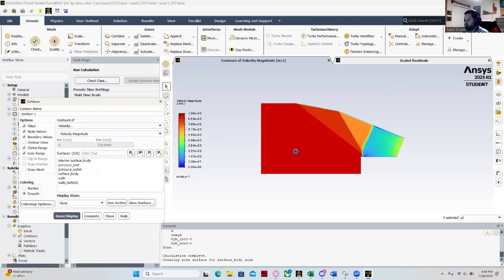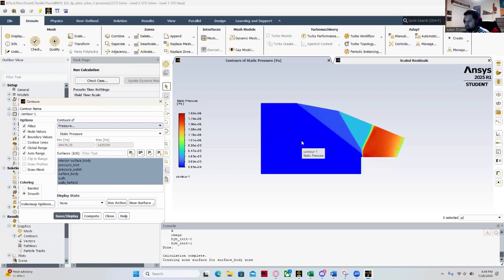Velocity contour is going to look very similar. First oblique shock, second oblique shock, normal shock. It's a little attached, but just for the sake of the video, we'll keep it like this. Next we go to pressure. Pressure is pretty much going to have the opposite effect. It'll start low, and as oblique shocks occur, it'll get a higher pressure.